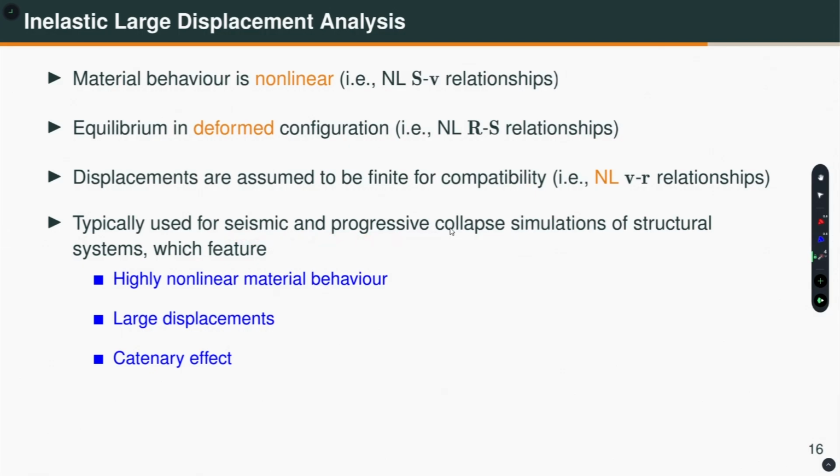Let us say you have a building where a terrorist comes and puts some explosive close to a column. The column is destroyed, then what will happen? The building is a statically indeterminate system, so the load will try to redistribute, and then the building may or may not collapse, but it may form a catenary action. So it may collapse progressively.